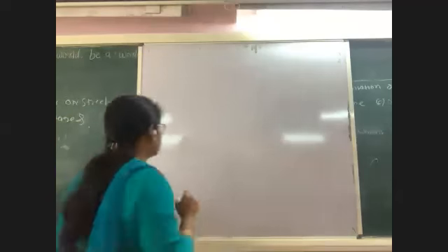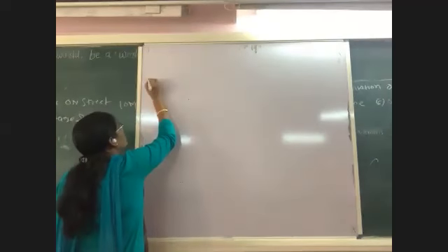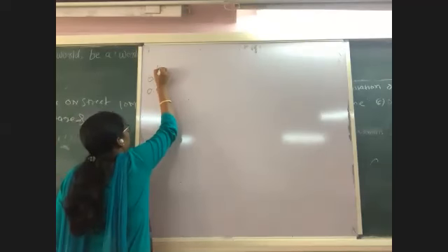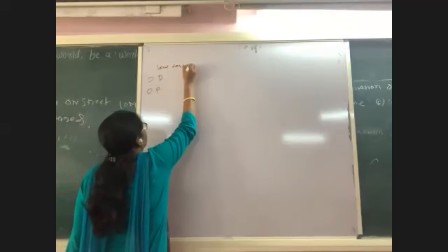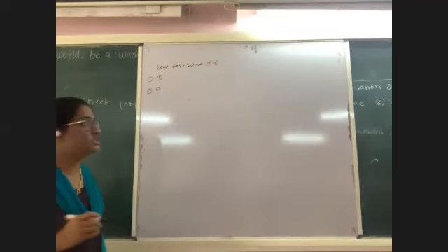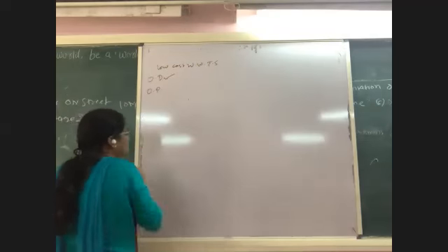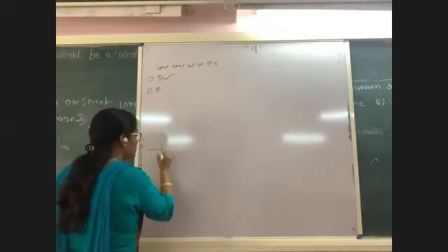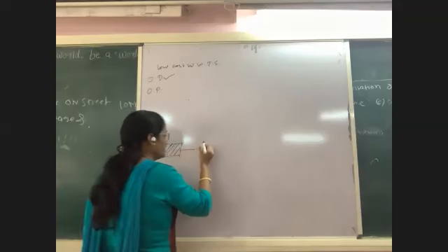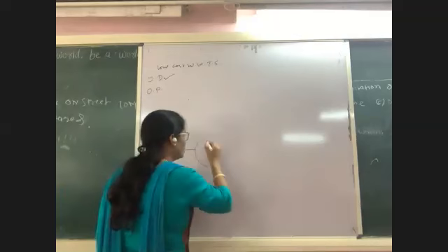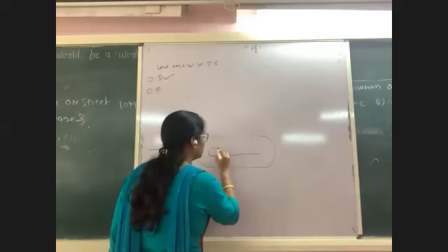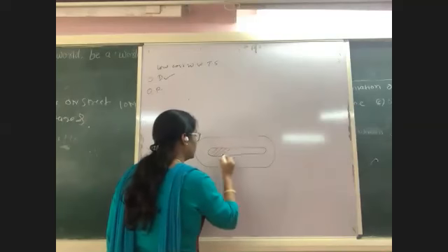Okay. In the last lecture, we saw the oxidation ditch and oxidation pond. So we were studying the low-cost wastewater treatment systems. In the low-cost wastewater treatment system, the first system we discussed was the oxidation ditch. In an oxidation ditch, there is a requirement of screening. Then the wastewater will go to the oval-shaped tank. Intentionally, it has to be designed oval-shaped to reduce the cost required for the movement of the wastewater in it.